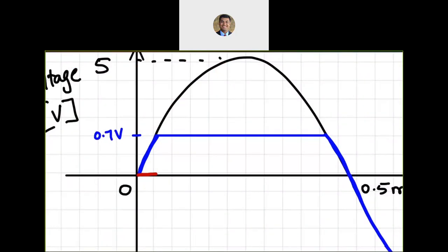And then as the voltage increases beyond 0.7, up until say that point, the voltage across the resistor is also going to increase in the same manner. Again, it will do the same thing until that point there. So I'm essentially just subtracting the two lines and getting that.